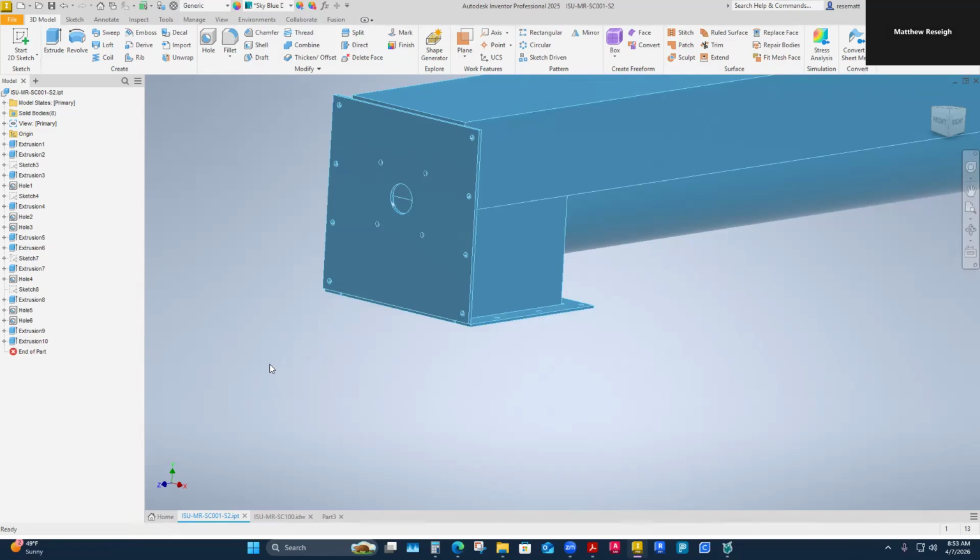A welded stud is sometimes spot welded on, and they sometimes come with a little ceramic ring around the end where the welding happens. It's a little flux ceramic that allows it to make a good fusion, because even a spot welder can be prone to contamination in the weld zone because it is liquefying.